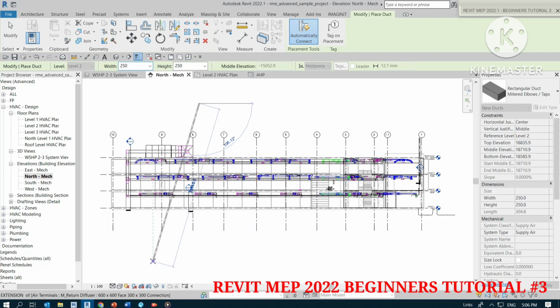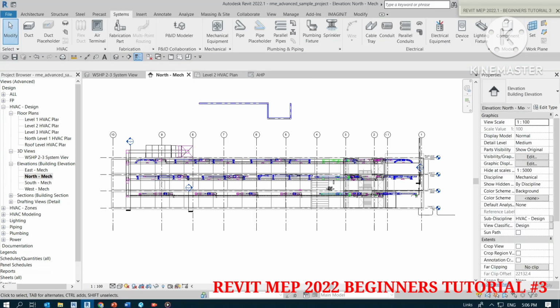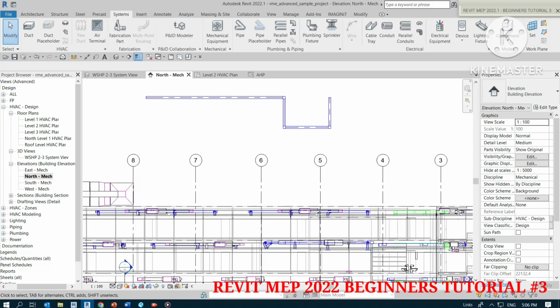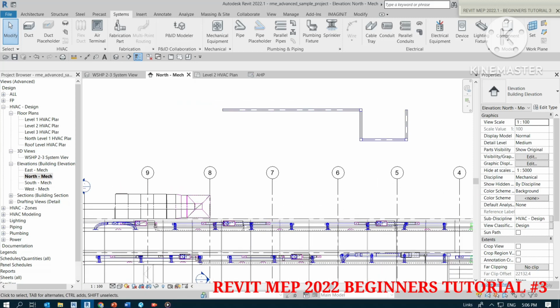I can just click once on the window, for example, like that. See, I clicked one point. Now what does it say? It says enter the endpoint. It means you are putting the endpoint of your duct. So I'll just click here, and another point here, and another point here again. Basically your status bar always gives you hints or tips on what to do. Let me just cancel this tool for now by clicking Modify here.